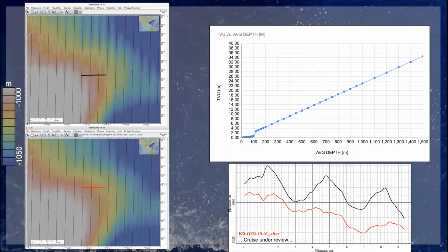Finally, this cruise is an example of where corrections were necessary to dampen the artifacts, where the vertical offset is within IHO spec, but the overall quality of the data is poor. Because the seafloor is so flat, this artifact really stands out, creating this washboarding effect that may be easy for a trained eye to understand, but risks misinterpretation by a less informed data consumer.